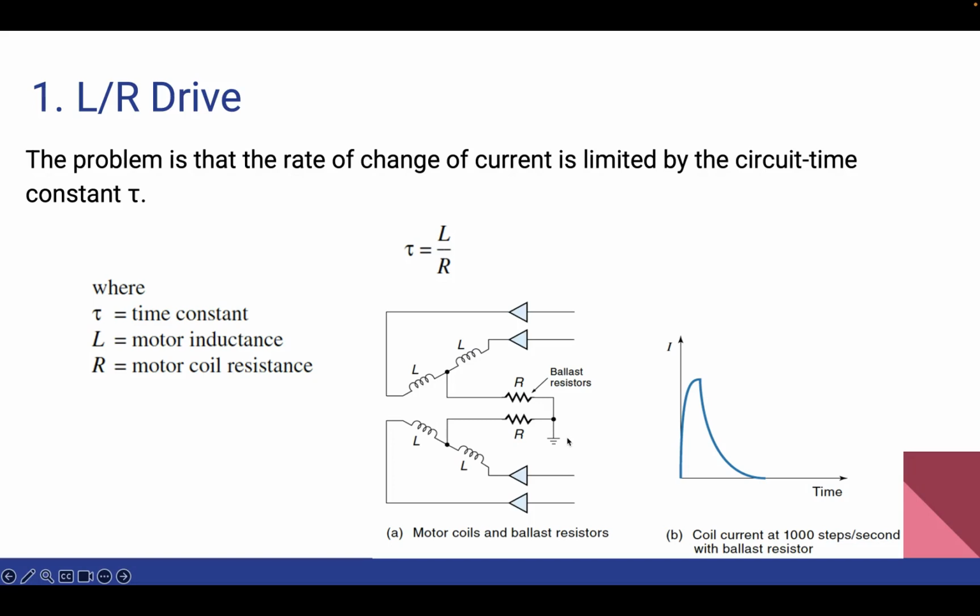The answer is that the electrical time constant represents the time it takes for the current in the winding to reach 63% of its rated value, and this value is derived from the system step response, where 1 minus e to the power minus t over tau signifies the time constant. A lower time constant indicates that current flows more quickly into the windings, which will enable the motor to reach its rated torque faster.